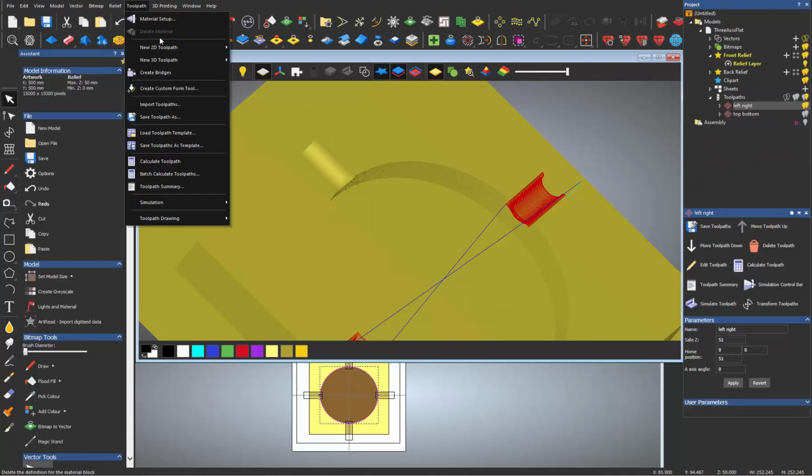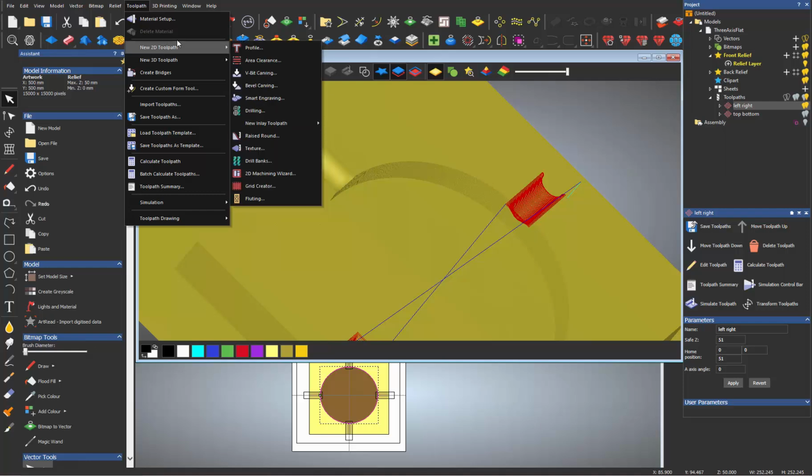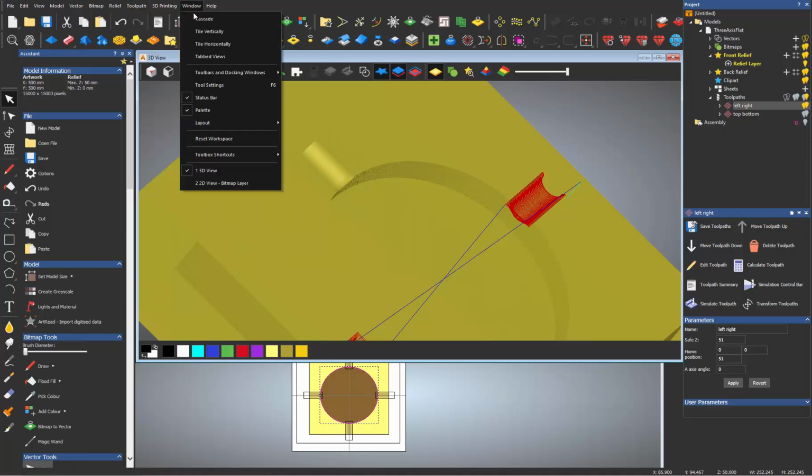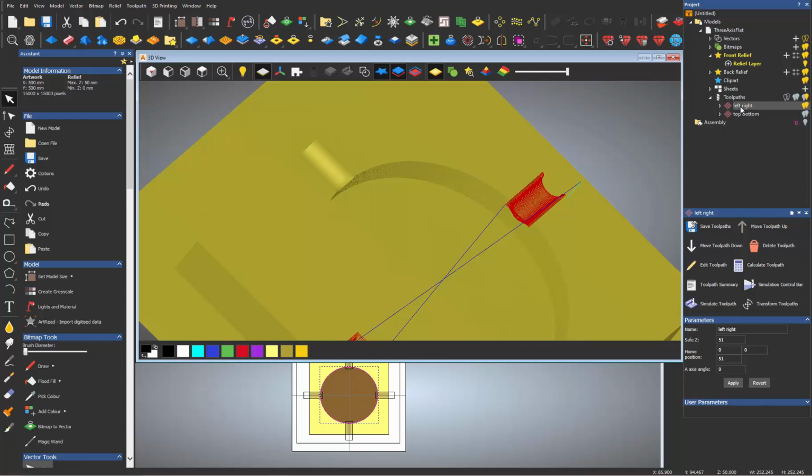So we would do a toolpath. I always use 3D, but you could do a 2D pocketing toolpath because all it is is just a flat. Do a couple step down roughing bits, leave a little extra material to come in here and do a finish bit with your 1-inch ball nose and clear that out. And for these toolpaths here, just to show you what I did with them.